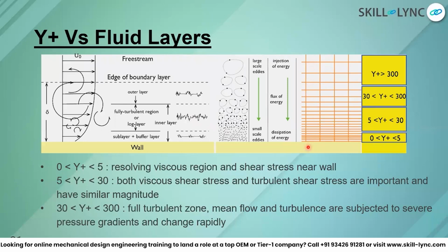So it's not like you are starting from a uniform mesh. If you are concentrating near the wall, you have to have a fine, good mesh to resolve everything, and away from the wall, you have a coarse mesh. The reason is that the energy dissipation or flux of energy near the surface is really hard to simulate and changes drastically.